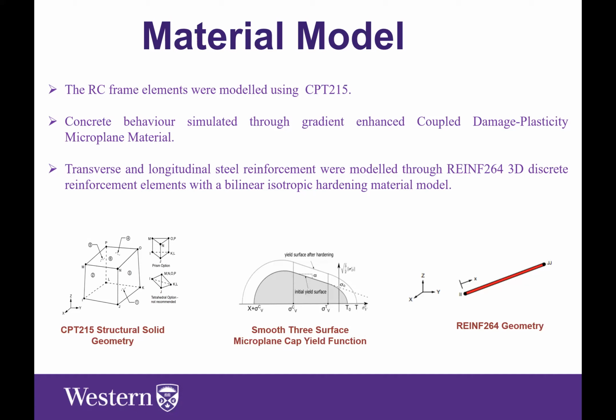Instead of using a normal stress-strain relationship, I used a material model that allowed for tension caps and compression caps. This provided a more stable numerical solution for implicit finite element algorithms, and it was also less dependent on the mesh and more accurate. So that's why it was chosen.